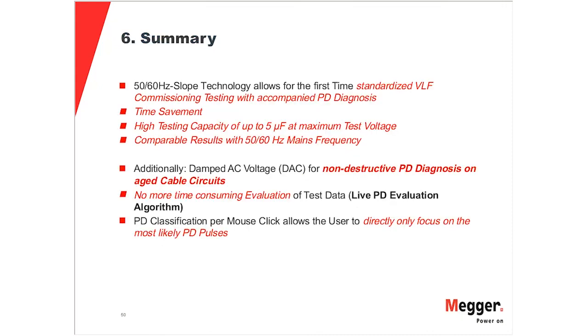Finally, after that, the customer was convinced that doing preventive maintenance means that you have to carefully choose the right waveform and the right equipment, so that it is giving you the results which you want to get. And again, you want to see results which are reflecting the reality. And the indication is clear. DAC and slope technology are reflecting the reality, while sinusoidal VLF does not reflect the reality.